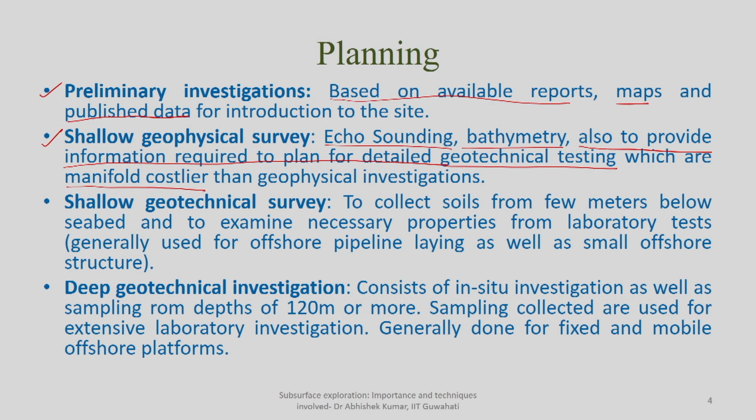So, there is very important decision making required before you go for detailed investigation, because once you do detailed geotechnical investigation, you have to arrange assemblies which are required for deeper drillings, maybe sampling and interpretation, and everything most of the time is done nowadays at the site itself.